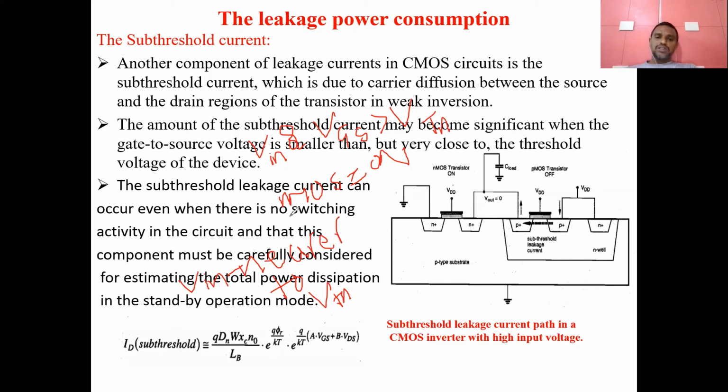For this condition, if Vin is equal to 0 or negative, there is no problem, because the NMOS transistor completely goes into the off condition. At the same time, if Vin is greater than VTN, the NMOS transistor completely goes into the on condition. There is no problem with those two points, but the problem is whenever the gate to source voltage is approximately equal to, or nearer to, the threshold voltage of the transistor, because the transistor will conduct partially.